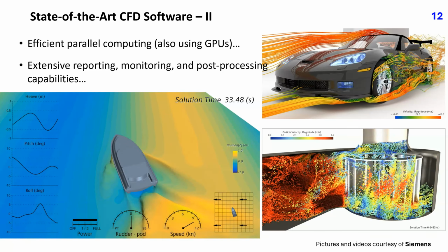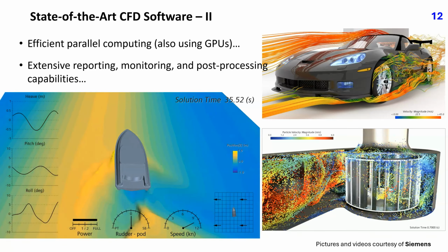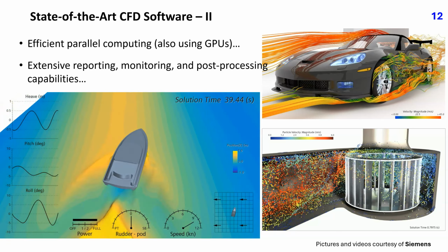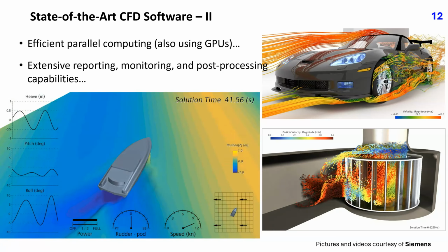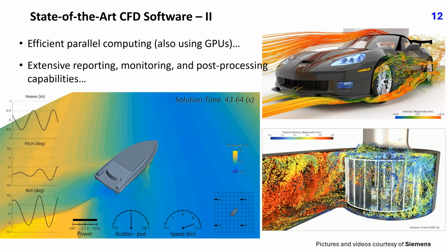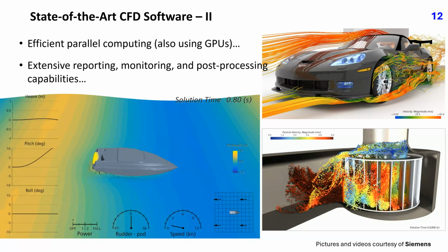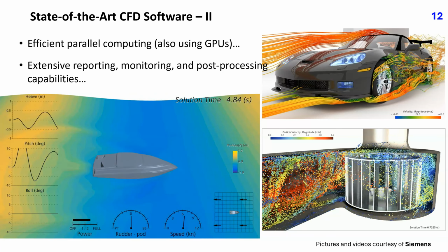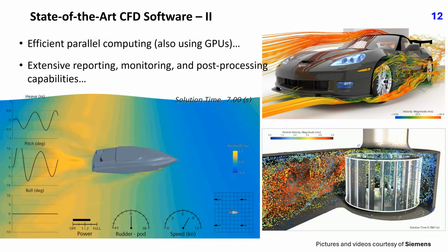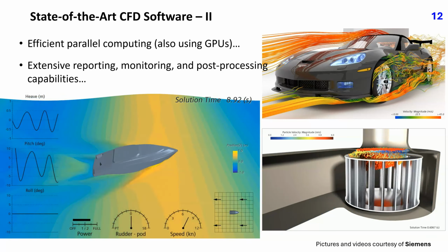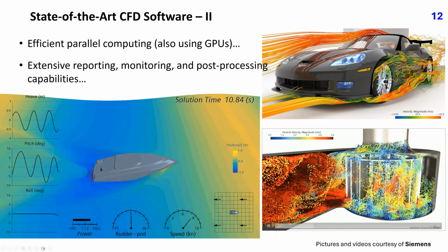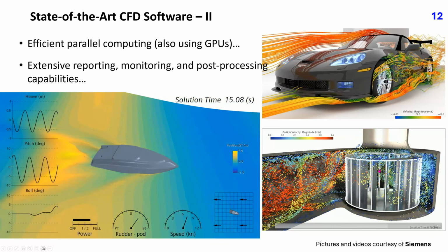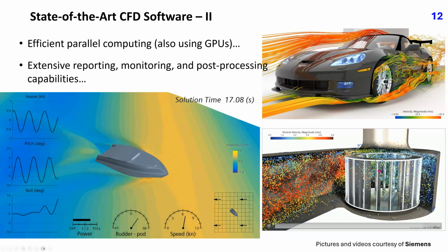Such simulations were until recently only possible using inviscid flow models, but those are not sufficiently accurate because they do not account for viscosity, turbulence, and breaking wave effects. In this simulation, Reynolds-averaged Navier-Stokes equations are solved and the free surface can break, eject droplets, and trap air pockets. Cavitation on propeller and rudder can also be simulated. Finally, this animation shows visualization of a complex flow in a turbomachine.